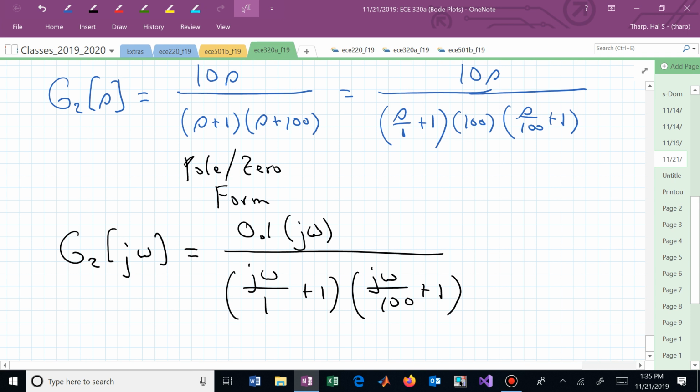And they give you a Bode plot and it's flat at low frequencies. Is that true for this transfer function? No, you're supposed to be sloping up from the bottom due to that 0 at the origin.